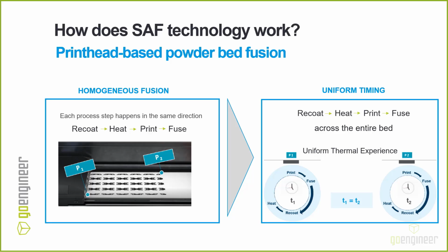And so how does SAF technology work? This is a powdered layer by layer additive manufacturing process in which parts are created by fusing selected areas of the powder a layer at a time. A layer of powder is deposited to recoat the previous layer, and parts are defined by jetting high absorption fluid into fine featured shapes with the industrial piezoelectric print heads. An infrared lamp passes immediately after, causing the powder particles to heat up and fuse together where the fluid has been printed.